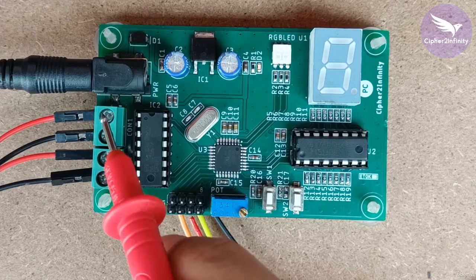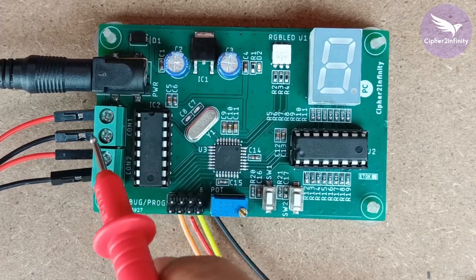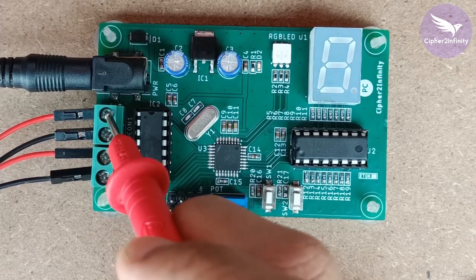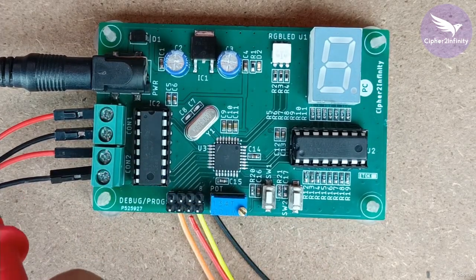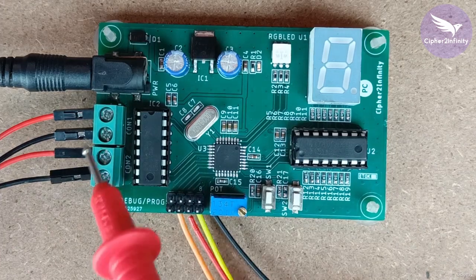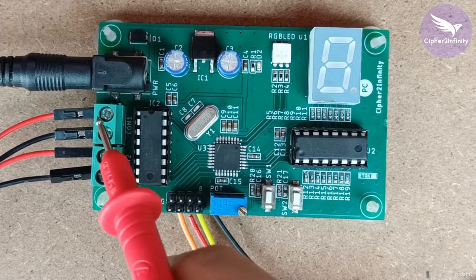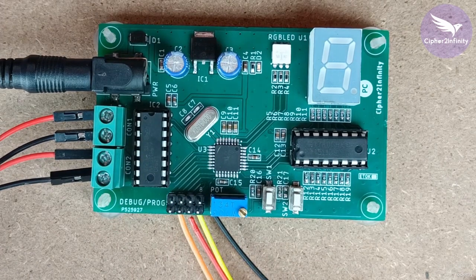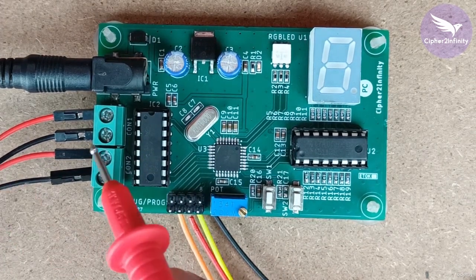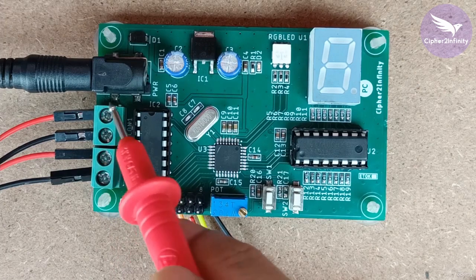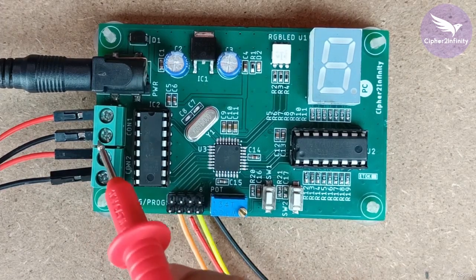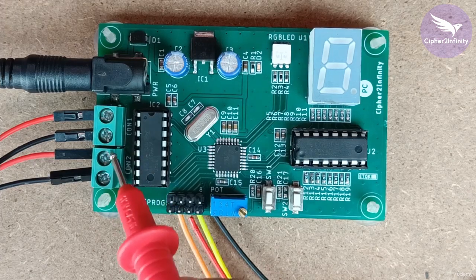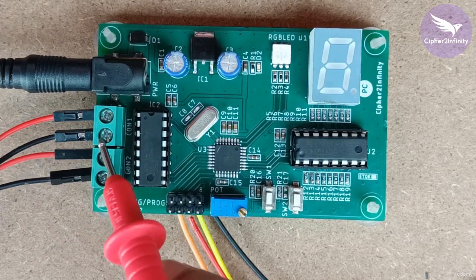If still the motors are not rotating, then put your multimeter in continuity mode, and check the continuity from this point to the point where this wire is connected on the motor. This ensures that there is proper contact from this point to the motor point. In the same way, do this for all 4 wires, and this will give you the surety that the contact from the PCB to the motors is proper.